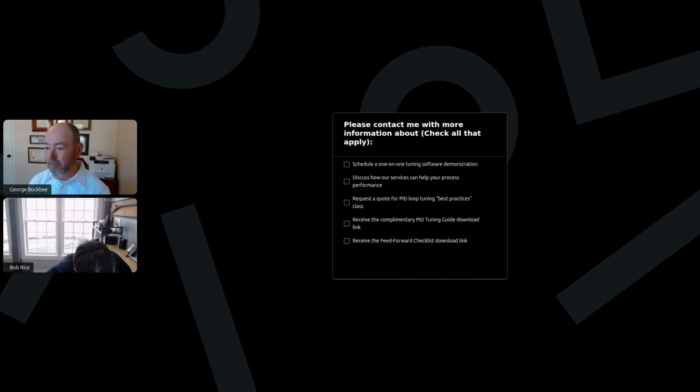One more here. I have a feed-forward flow to level. It works okay during normal operation, but sometimes operations take the flow in manual to address a process issue, and then the feed-forward to level is much too aggressive. Is it a good practice to disable feed-forward sometimes, or should I just add a filter or detune? Thanks.